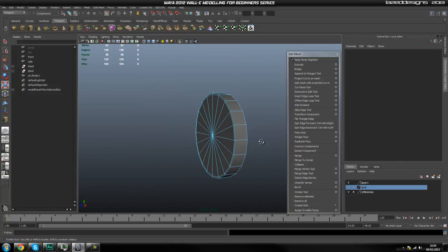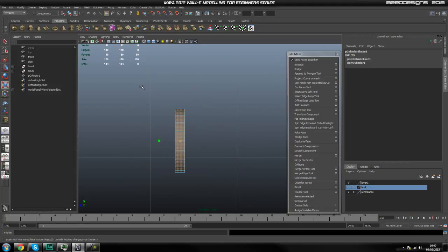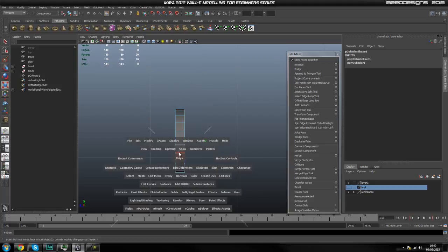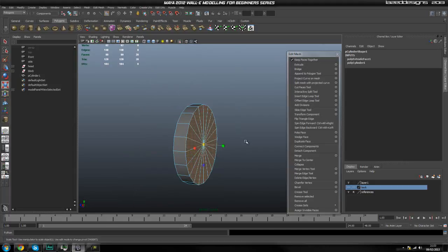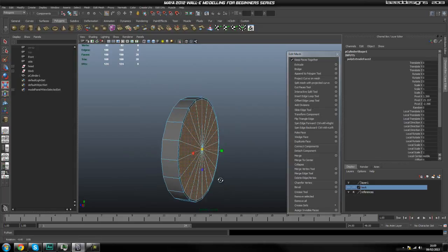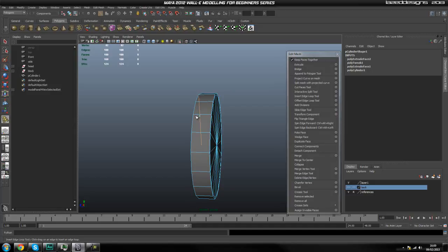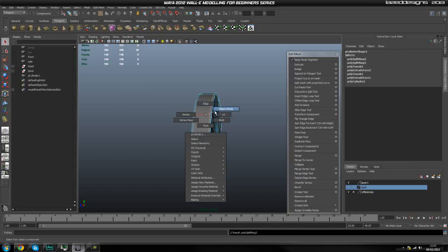I'm going to undo all that because we've done our selection wrong. So I'm going to select all those, deselect all of these, go into my perspective mode, hit extrude, scale, and drag out just a tad. And then we're going to insert an edge loop, going around, not there, but here, and also one going around here. So now this will hold its shape.